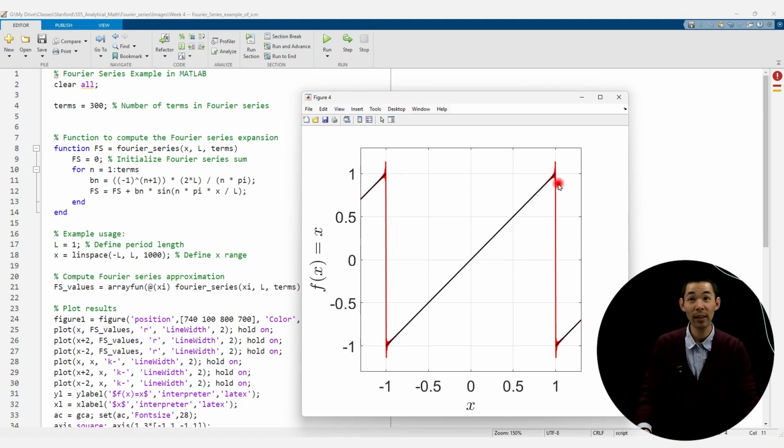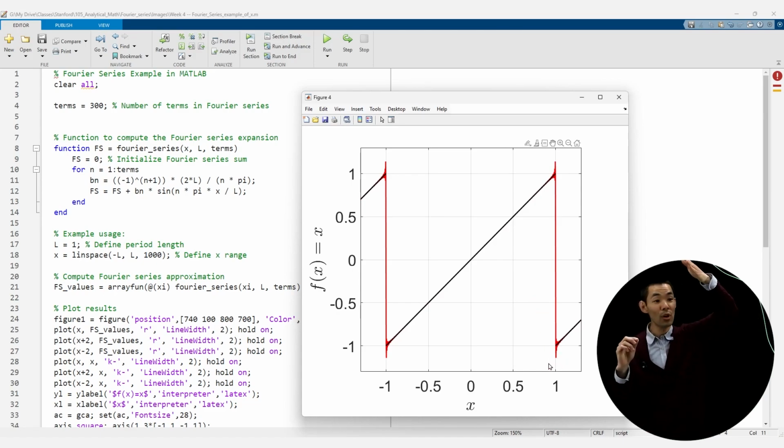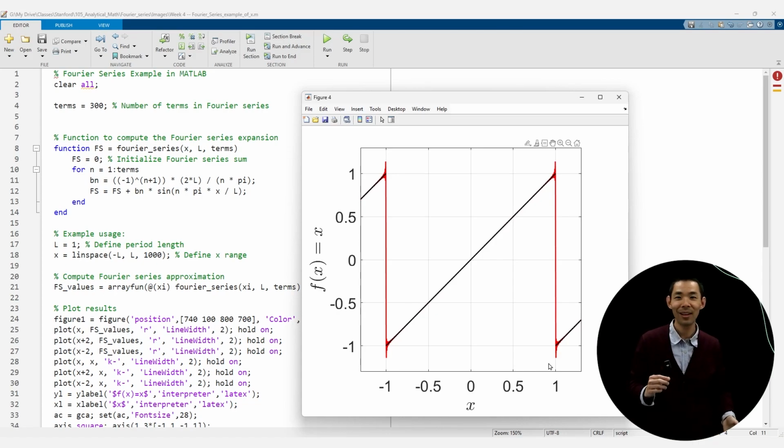And also, the reason why the overshoot exists here is that the sine function is a periodic function that has to go from a value of 1 all the way back down to -1, because it's periodic. So it goes up and then boom, oh no, I gotta go all the way down. But to go all the way down, a sine has to use a high frequency thing to curve around. And so it can't just bluntly stop and then turn back the other way. It's curvy, so it goes and overshoots and then it curves down. And that's why it overshoots. Okay? It's called the Gibbs phenomenon.